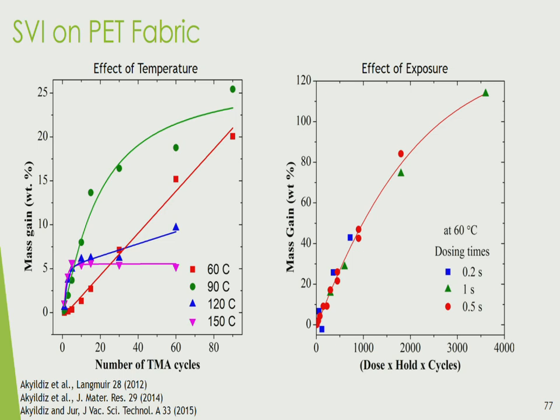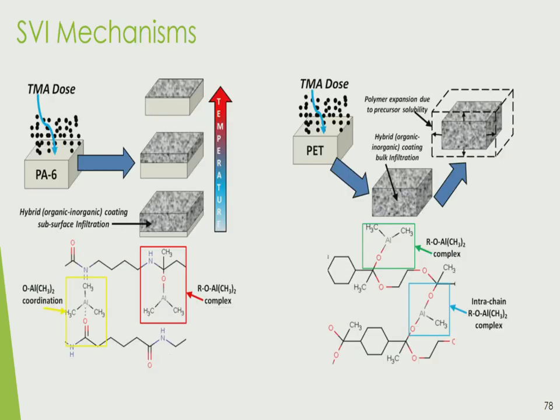The first time we did this process, we placed it in the reactor, we exposed a lot of TMA to it, and we didn't do the water step afterwards. So we purged everything out. We took the sample out, and it literally caught on fire. It was really impressive. There's a lot of TMA in there. Don't do that.